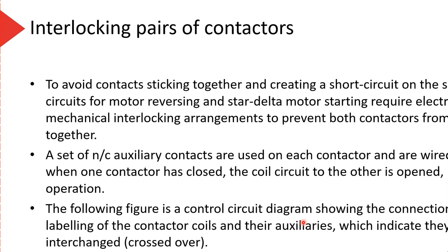So we will have the auxiliaries on each contactor wired in such a way that when one contactor is on, the other one can't be on, and vice versa. So even if I push the forward button and the reverse button together, when I switch one on, it's going to take power off the other one. So I physically cannot switch the other one on until I've switched the other one off. One day I will show you this stuff in the practical lab. I'll show you what I mean by that, and we can actually demonstrate it one day when the world is back to normal.